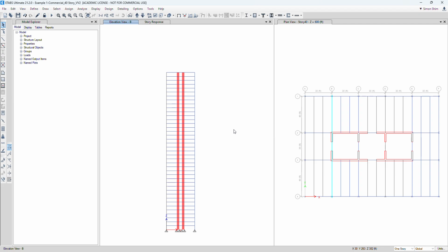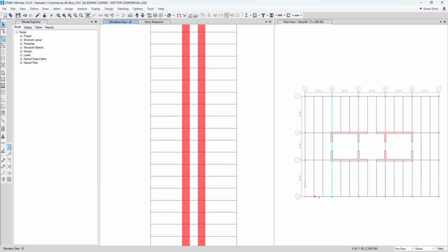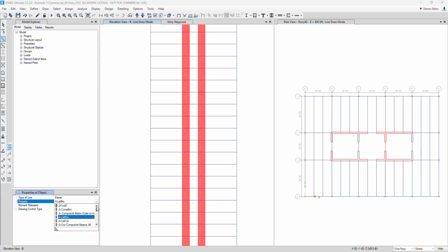Okay, this is my elevation. See the B? So, I'm going to randomly choose the middle height. Thing is, for section properties, I need to look at which section property I'm going to use. Maybe auto selection, or for now, for example purposes, I'm going to choose W. Let me see what is available. Okay, all right, W14x426. I just chose one significant section, and the moment release is a pin connection, right?